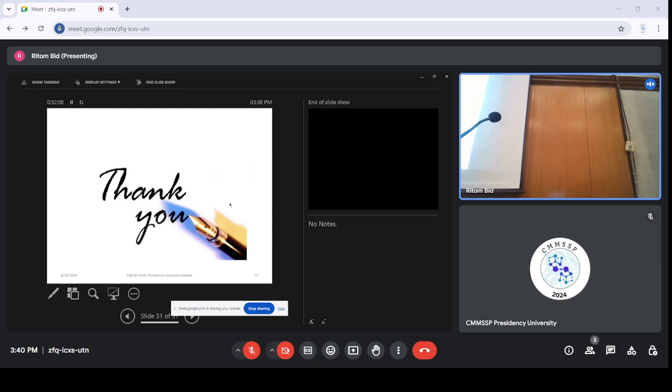Now, when we go to the superstrate configuration, we have the substrate, it's a glass or quartz, whatever we make, then you deposit the zinc oxide or high bandgap material, and then the absorber layer. The absorber layers are more stable, and light is entering through the substrate. So the zinc oxide or the high bandgap materials are not getting exposed to the environment. So in case of stability issue, the superstrate structure is more usable.